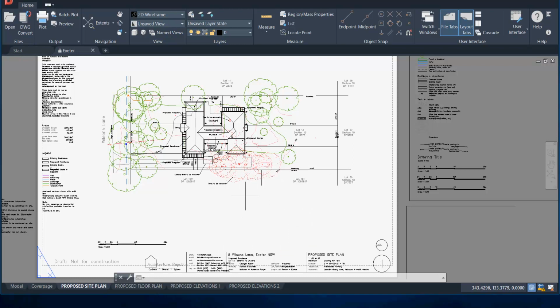Well, if you receive a DWG file from an architect or a survey firm, the first step that I would take is to install Autodesk's DWG TrueView viewer. I'm using it now and looking at a typical file, and it has a little symbol on the bottom left, like a set square, which tells us we're in layout space.